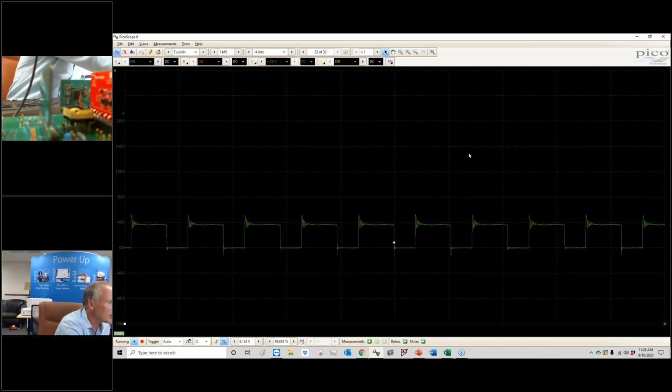A dual flyback, you shouldn't need a snubber. Okay, I see lots of app notes where they don't put snubbers on the secondary diode. They say, we're going to go discontinuous mode, so the secondary is going to naturally commutate. What about in a transient? During a transient, you'll be hard switching that secondary rectifier. When you do that, the ringing can either destroy the part, or that ringing gets into your controller and you're going to get into some strange burst mode. Maybe it'll start hissing. If your converter is hissing, it might be because you don't have your snubbers in place.